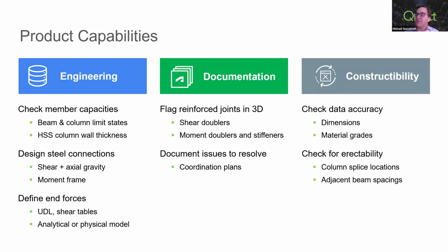The forces being used, I mentioned earlier about using UDL or shear tables or the forces in the model. Some of those industry experts that I showed earlier, they have always touted, engineers should put the forces on their drawings. Otherwise, the connections are going to just be over designed. And so that's why we have that built in to read that data from the Revit model.